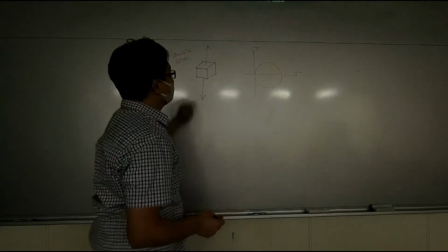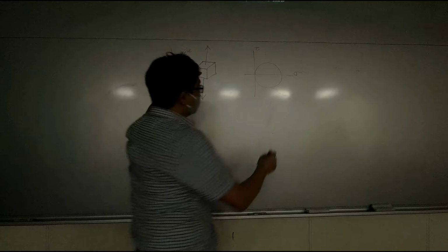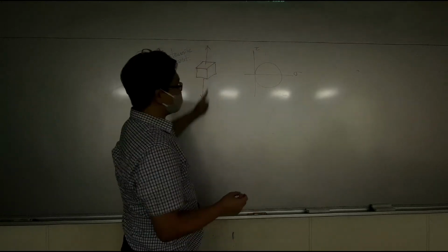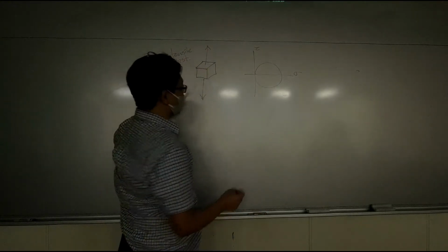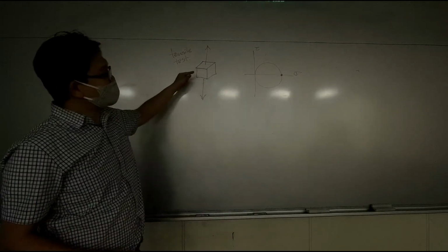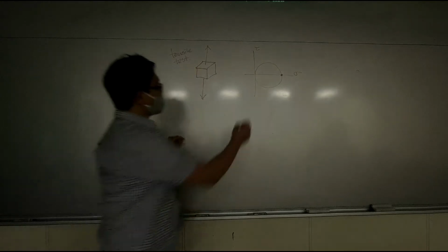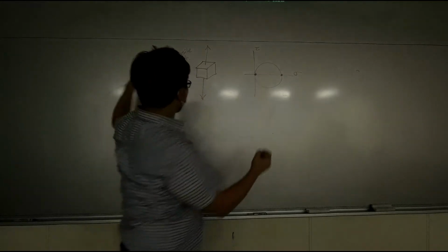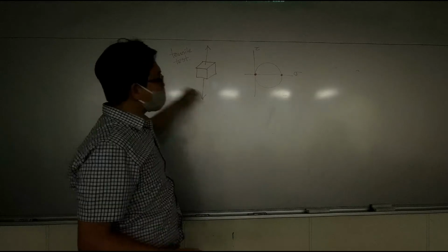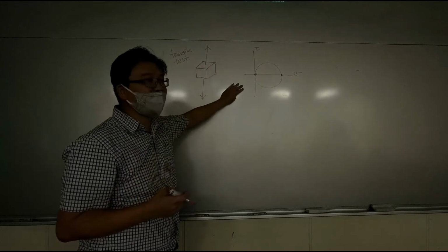Because if you try to plot out the load condition of this material, there's only normal stress along this direction, there's no other stresses. Then you will get a point along this direction and a 0 point along this horizontal direction. That's why the Mohr circle of a tensile test is always like this.